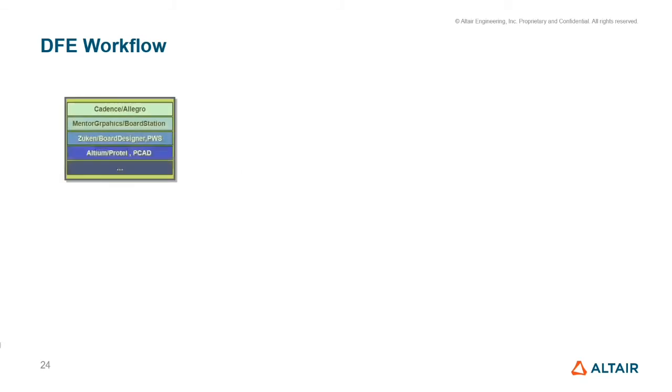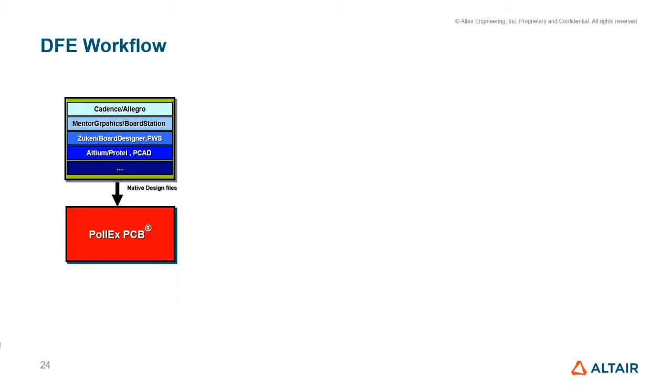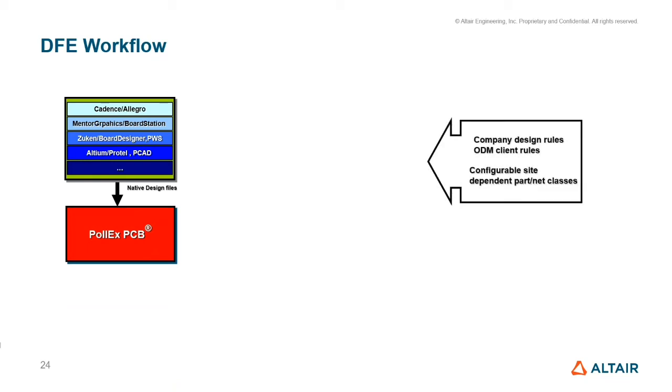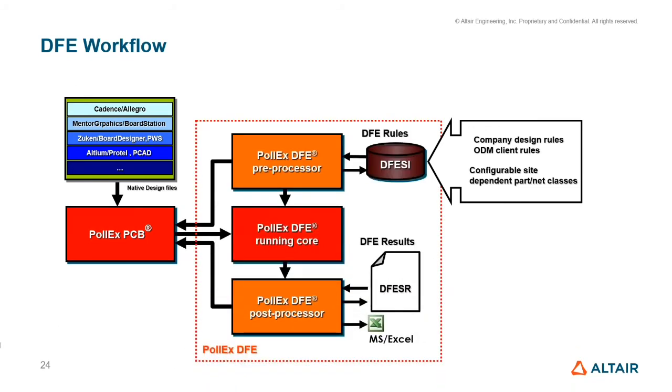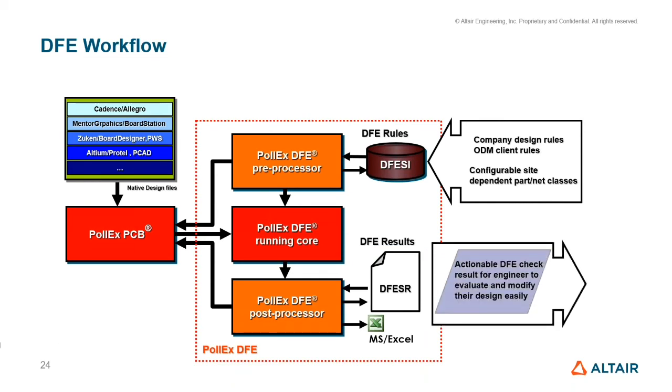Understanding the DFE workflow is crucial, and with Altair PollEx, it couldn't have been more straightforward. Well, you start by obtaining the design files and import them to PollEx PCB. The PollEx PCB modeler has an easy integration with a host of designer tools. Secondly, we consider the company design rules and the ODM client rules. These rules are integrated as DFE rules. Applying these rules to the design, we get the DFE results, which are then sent to the engineer to evaluate and modify the design, or sent to the manufacturer if no modifications are needed.